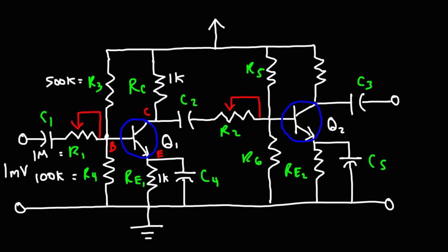Because we're dealing with higher voltages in the second stage of this circuit, we're going to make R5 lower. I'm going to make it 47K. You could make it 50K if you want to, but you usually don't find a 50 kilo ohm resistor. Chances are you'll find a 51 kilo ohm resistor. And for this, chances are this will be a 510 kilo ohm resistor. Now I'm going to make R5 equal to R6.